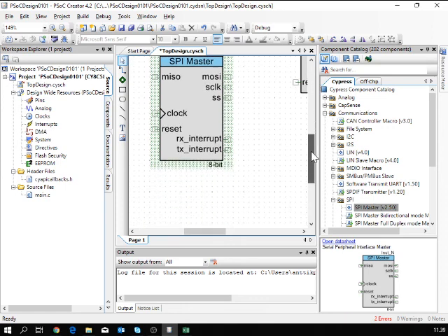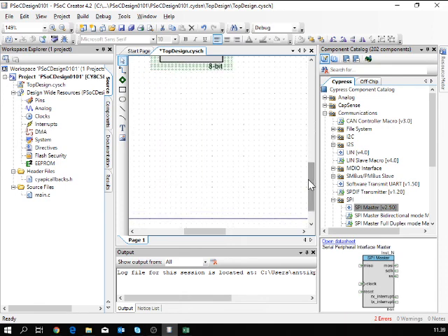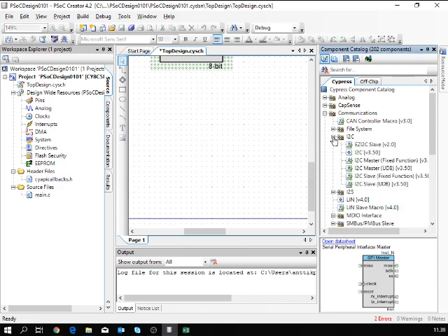Okay, then I2C. That first one is slave, meaning that the easiest way of using this circuit as a device is to have an I2C slave on it, for example for that A to D converter, meaning that you have software access to the data that some other device is going to read.